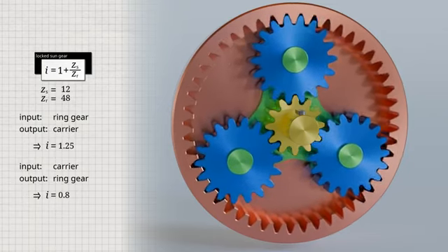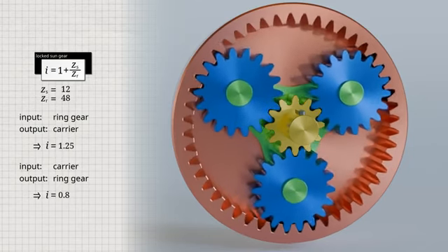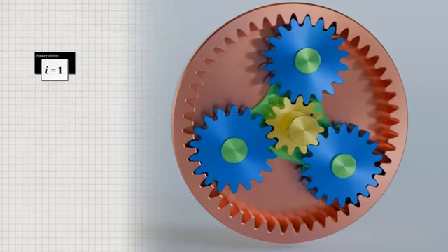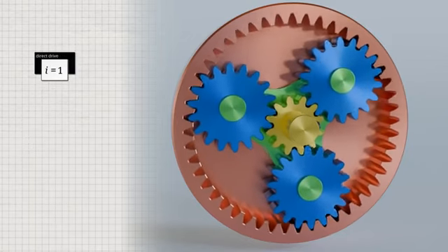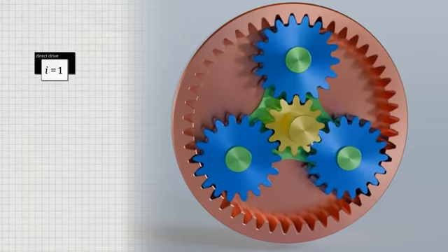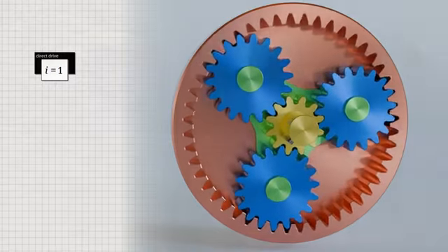With shiftable gearboxes in particular, it should not be forgotten that a so-called direct drive is also possible. In this case, all components of the planetary gearbox are firmly locked together. In this case, the transmission ratio is 1. Such a direct drive is used, for example, in 3-speed hub gears as the second gear.